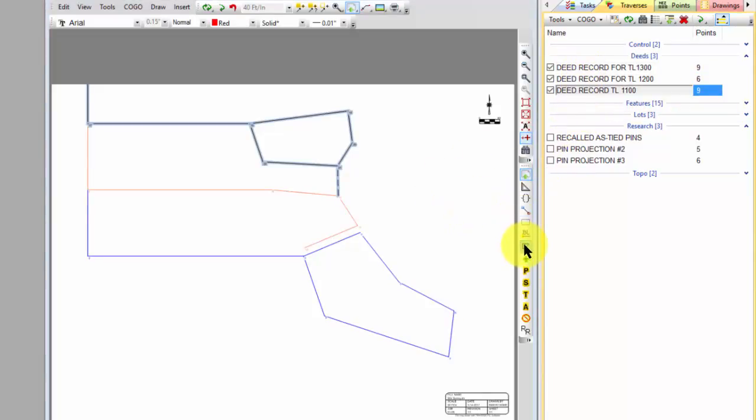And typically, I'm going to have to make at least one trip out here and tie whatever existing monuments I can find so I know what's out here. Right away, when we see we've got this gap here to deal with, and in this particular survey involves a boundary line adjustment to accommodate that, I know that I'm probably not going to be able to do it all in one trip. Probably going to have to go out there, tie down what's there, come back and might have some more research to do. I may want to put together some different scenarios for how the monuments that I tied fit with the direction I need to go on this survey.